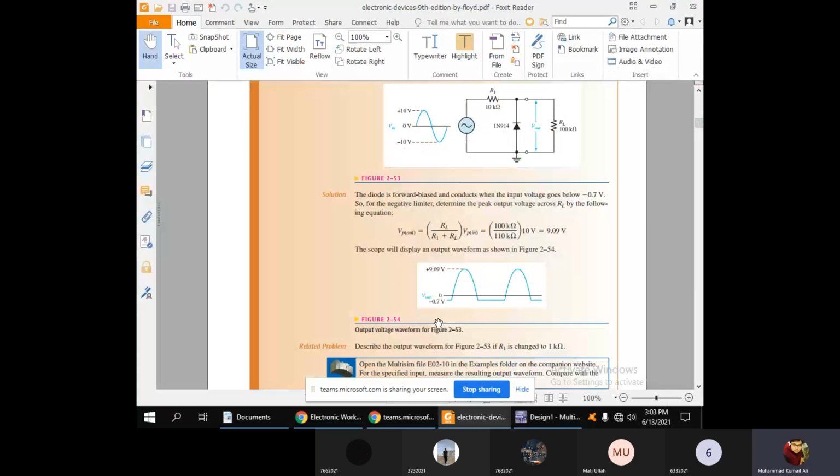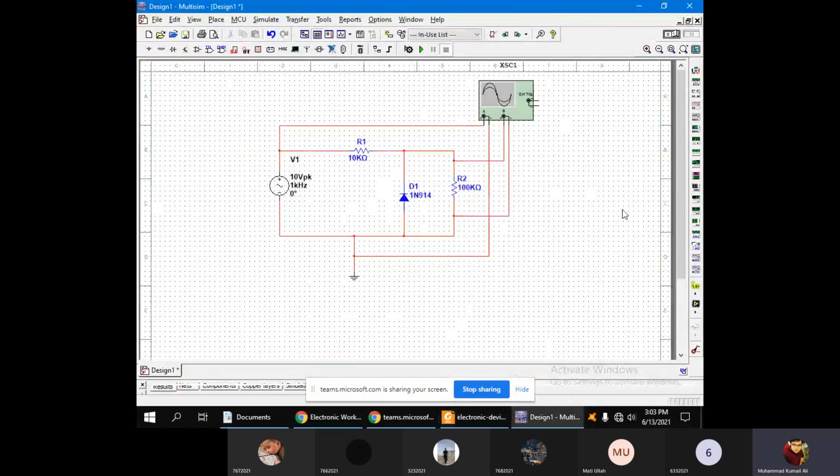Circuit is completed. Now click on the run button. Its shortcut key is F5, so you can also simply press F5 on the keyboard to start the simulation process, or you can simply click run. Now the running is started and you have to double click on the oscilloscope to see the results.